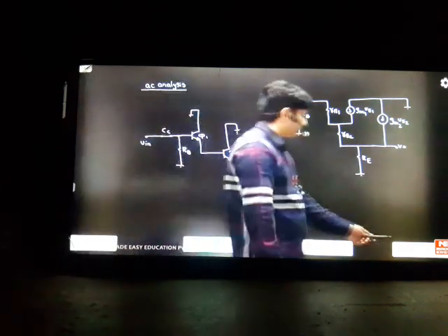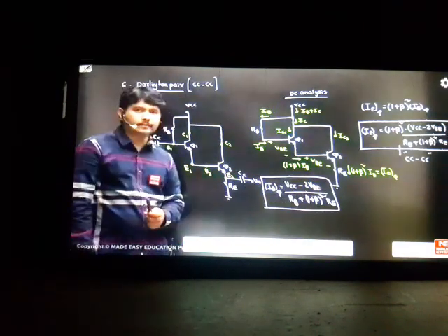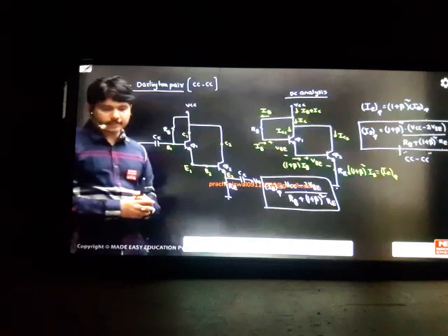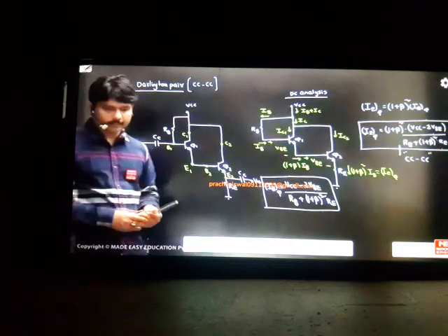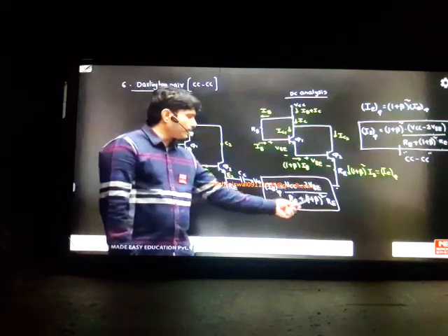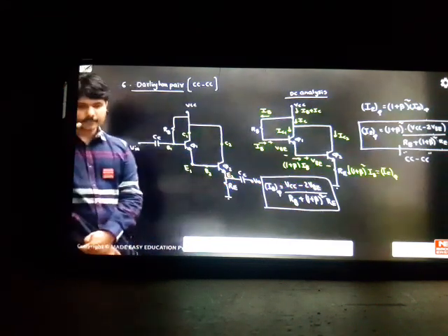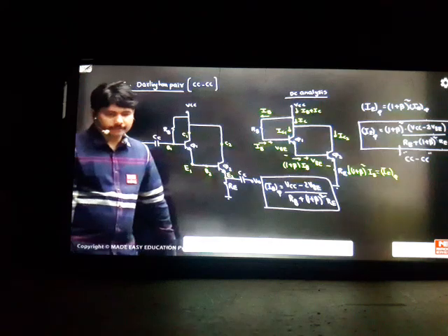So I think on the previous slide, somebody has not completed noting that. So please note it first. Somebody is asking to read this formula. IBQ is equal to VCC minus 2 VBE. I said, Rahman, I think you are asking. Who is asking this? Samresh. VCC minus 2 VBE divided by RB plus 1 plus beta square into RE resistance. That is the base current. Okay. Please Rahman, complete it quickly.